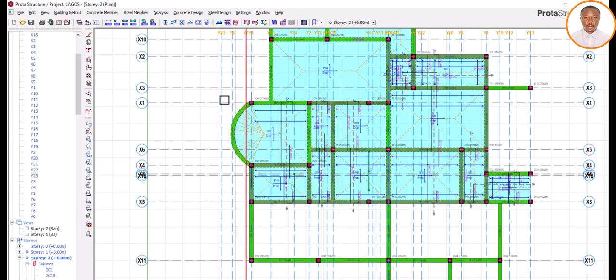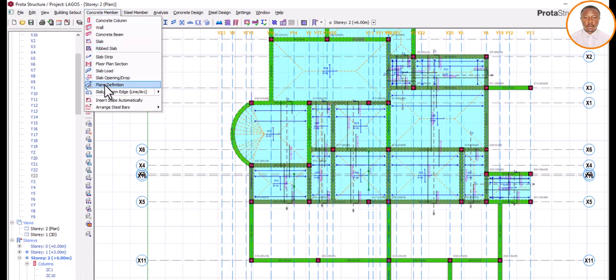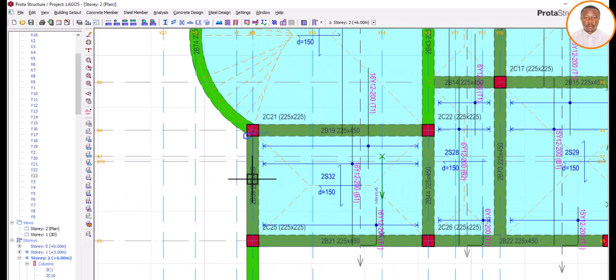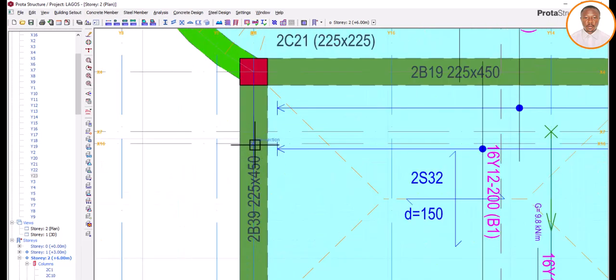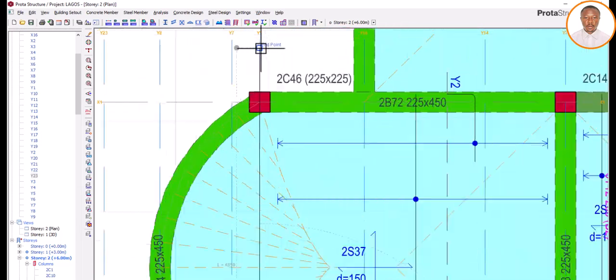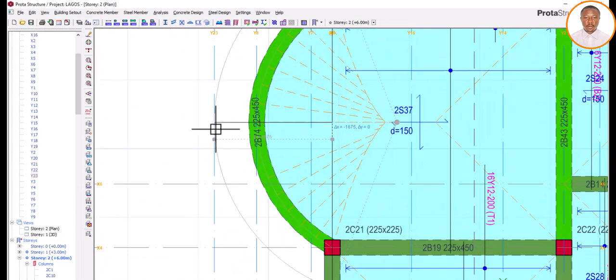Now I go back and click on this and pick my tool. This time around we are not picking the first one, the slab/column edge in bracket line/arc close bracket. No, we are going to click on the one that has to do with the slab/column edge in bracket arc. So I click on it and come to this place where my 600 is, and click. Also come to this place where my 600 stops, endpoint, and then extend it to where I have my 600.